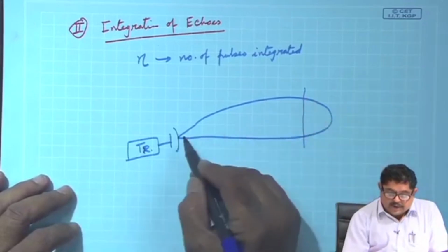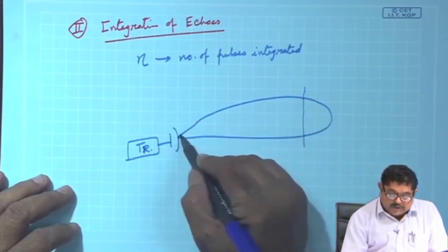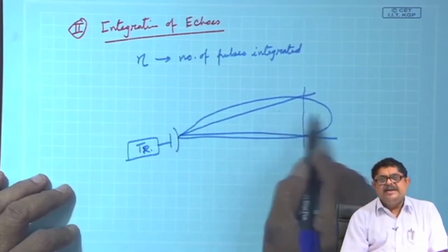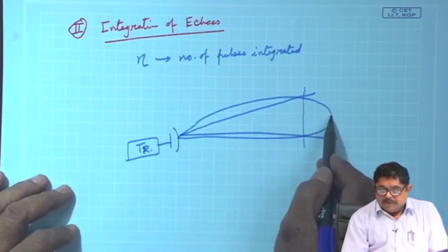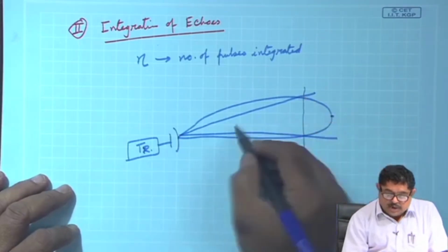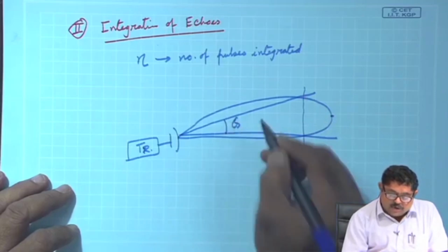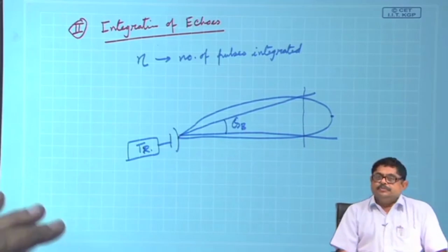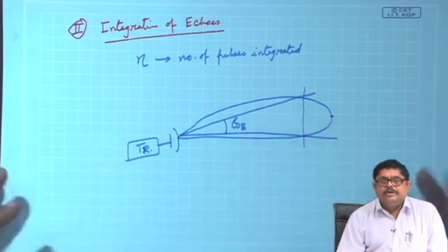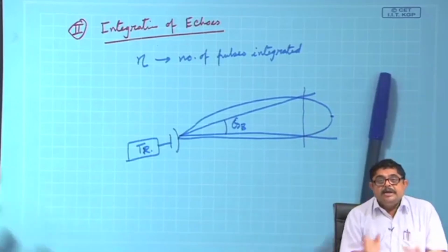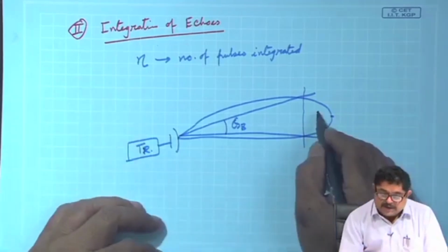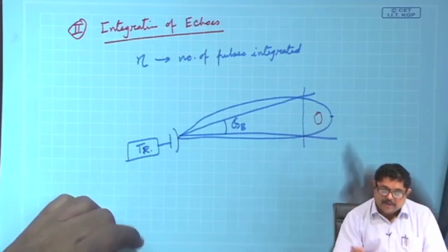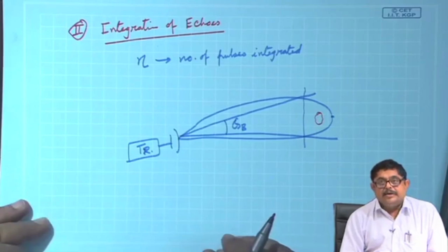There we have seen that basically there is a beam width, and we define it; there are various definitions, such as 3 dB down from this peak, etc. So, that beam width is generally called theta b, antenna beam width. Generally for power patterns we take the 3 dB beam width. So, that means if the target is inside this, we say that it is getting illuminated.